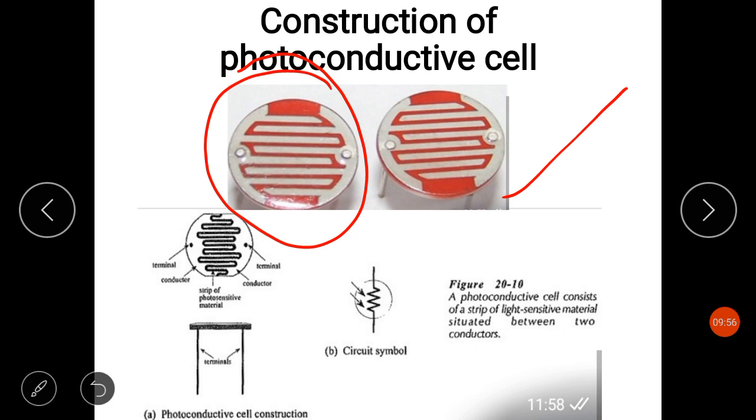So what is chemical sintering? Basically, sintering is a heat treatment process in which a large quantity of loose aggregate material is subjected to sufficiently high temperature and pressure to cause the loose material to become a compact solid piece. The amount of heat and pressure administered during sintering is slightly less than the material's melting point.